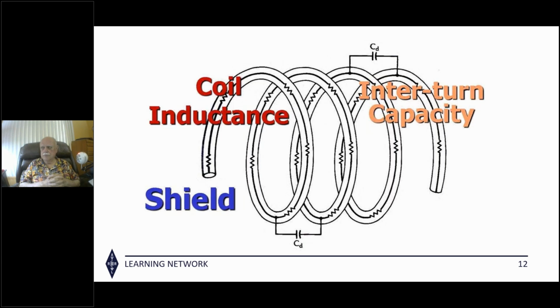Is a balun recommended for a quarter wave vertical? As far as I'm concerned, all antennas should have baluns on them. I put them on everything, because if you think about it, that quarter wave vertical against radials, the radials are just half of the dipole cut into quarters and spread out. It's still a dipole, and if you feed it with coax, it still has the 2 to 3 wire transition, and the RF will get back on the outside. So yes, a quarter wave vertical with radials definitely needs a balun at the antenna.